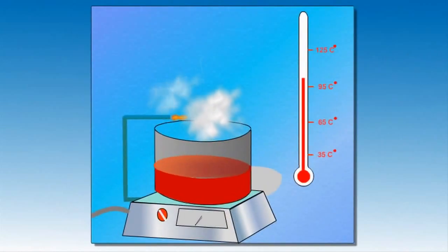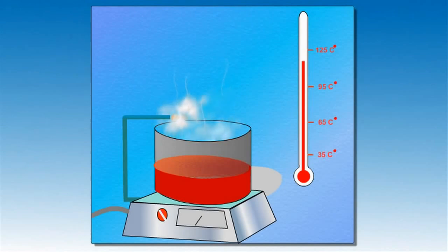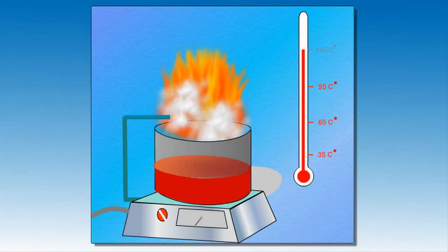In this example, we have the heating of a combustible liquid. Explosive vapors are created as the material reaches the explosive limits, creating the flash point. If the general atmosphere is increased to the auto-ignition temperature, fire or explosion will occur.